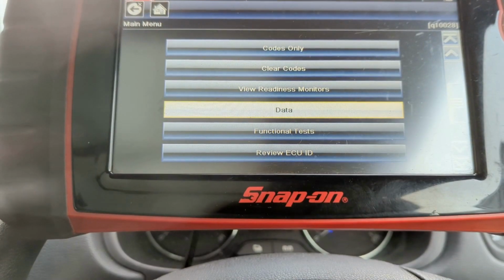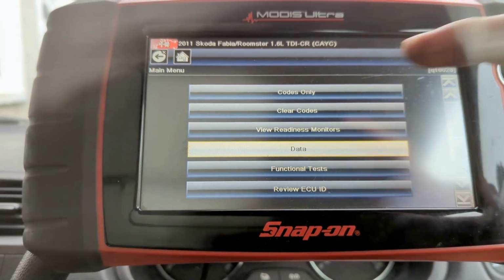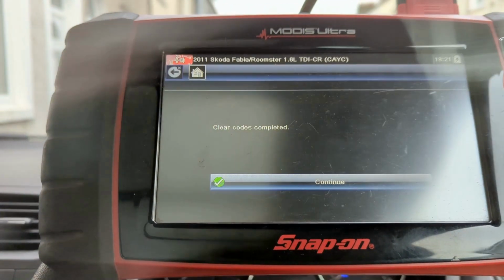There could be a lot to uncover on this one. Don't know if you can hear that. Apparently that noise went away with the EGR unplugged. I might look at some EGR data. I'll clear codes first. Right. Clear codes.